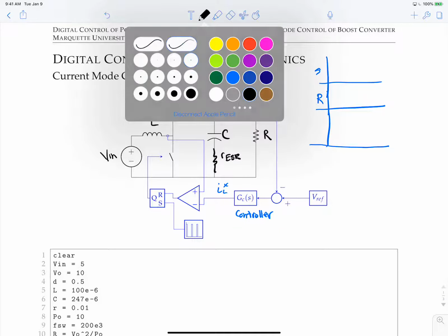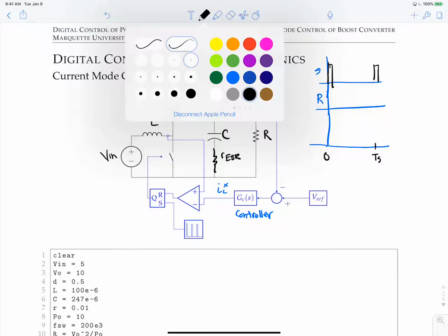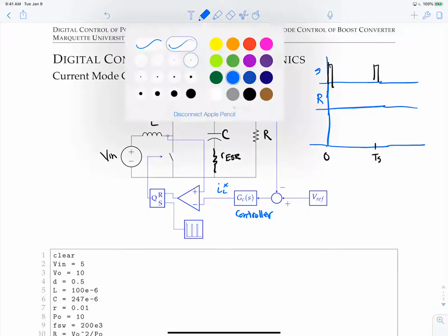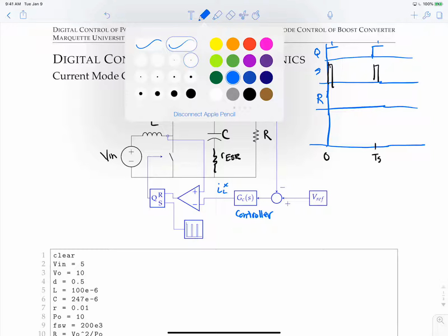So in terms of the set signal, that's generated from a continuous pulse generator, which at time TS always generates a small, really thin pulse, let's say less than 1%, and this happens indefinitely. And what that will actually do is generate Q, or turn on the SR latch. So right when set hits, Q will go to 1. Now, how do we actually reset the thing? Well, that is done through the comparison of the actual inductor current and the